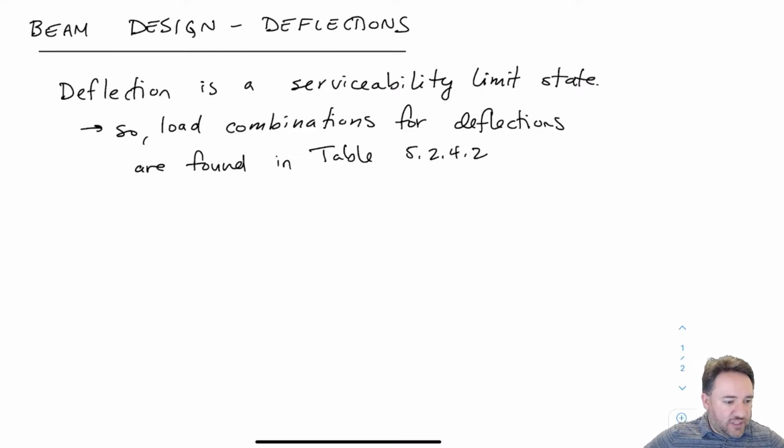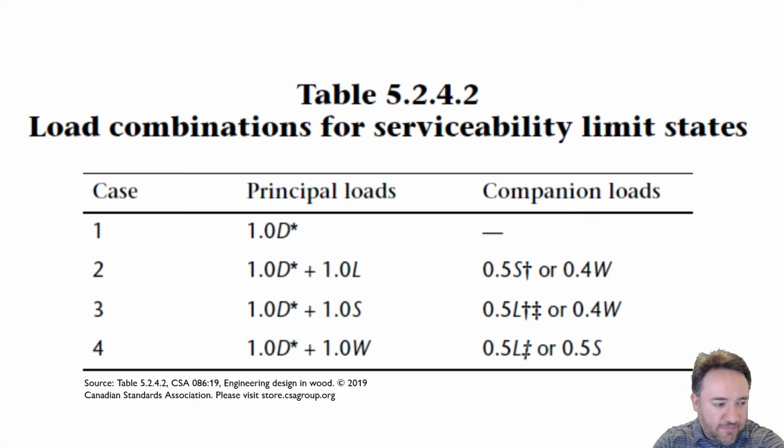Now in serviceability, since we're talking a lot about occupant comfort, that occupants of our building or other structure aren't terrified to occupy those structures, we do not actually factor up our loads. So here is the serviceability limit state table.